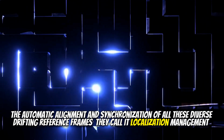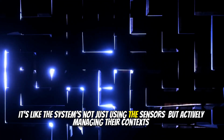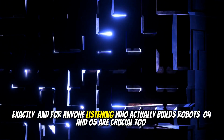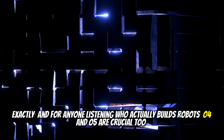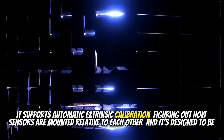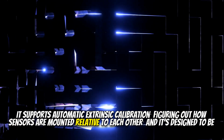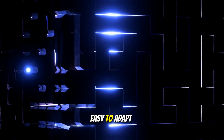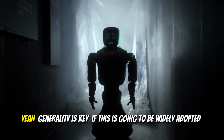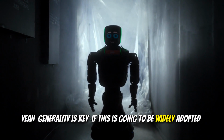They call it localization management. It's like the system's not just using the sensors, but actively managing their contexts. Exactly. And for anyone listening who actually builds robots, O4 and O5 are crucial too. It supports automatic extrinsic calibration, figuring out how sensors are mounted relative to each other, and it's designed to be easy to adapt. You don't want a solution that only works for one specific robot setup. Yeah, generality is key if this is going to be widely adopted.